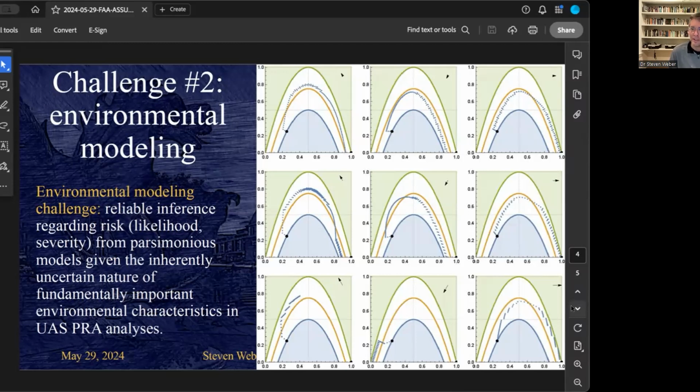The goal of the trajectory, as you see, is to get to the lower right-hand corner of the figure in all 9 cases. And the different trajectories under the different wind environments show that when the wind is light and even when the wind is moderate, the drone is successfully able to navigate the wind and overcome it. In the bottom panel, however, what you see is something a little bit different. When the wind blows to the northwest in the lower left corner, the drone ends up stalling. It ends up trying to face back towards the path that it is trying to get back onto, which is directly contrary to the direction of the wind, and ends up just stalled and unable to move forward.